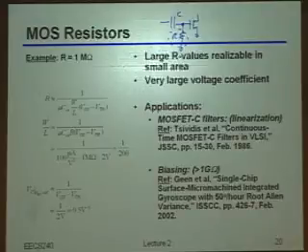The only reason I brought this up, by the way, is A, because this is an interesting effect we'll talk about a little bit later on in the class, but B, in this particular context, it just says you want to make sure that that resistor you use there is small enough that you don't have any problem with the leakage current basically destroying the DC bias you're trying to set there. But again, even if this thing varies by a factor of 10, as long as that current is, let's say, 10 or 100x higher than what the leakage current would have been, you're basically fine. So again, this is another example where even if it's really highly variable, you just want something that's basically big in terms of its value, but within a very small physical area.